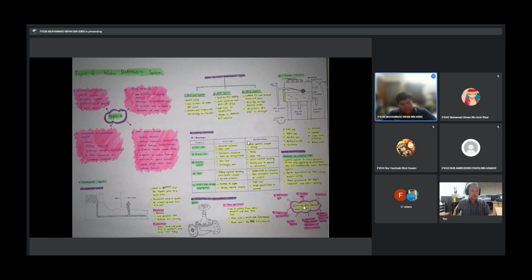The fourth one is non-revenue water. There are leakage factors, leakage procedure measurements. There are two things under this leakage procedure measurements, that is direct and indirect. Then the methods to control leakage, methods to detect leakage, piping design with Hazen-Williams formula. Okay. So there are three types of water distribution system, that is dead end system, grid system and the ring system.